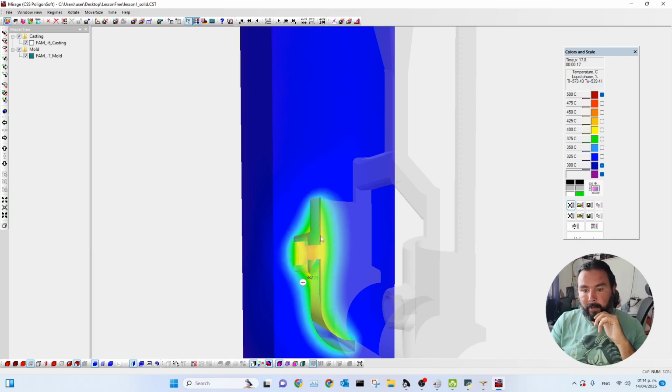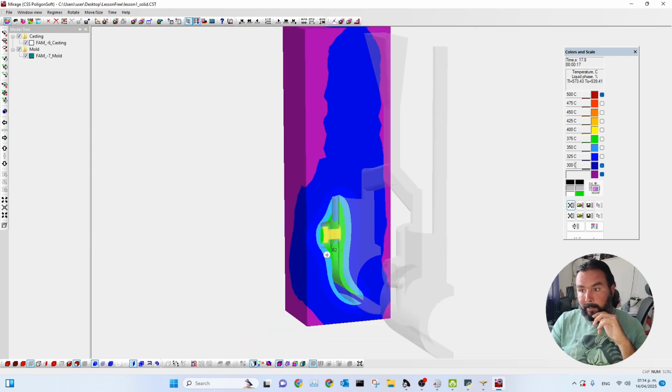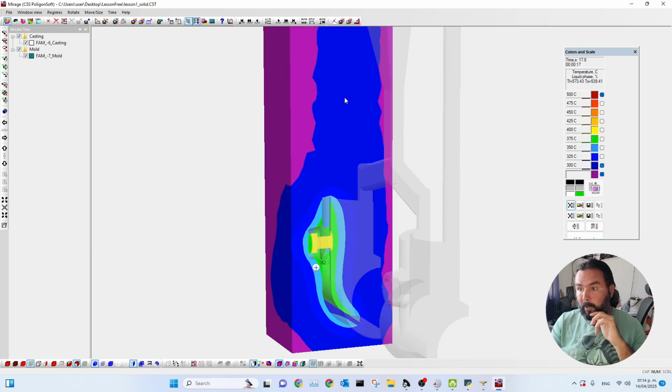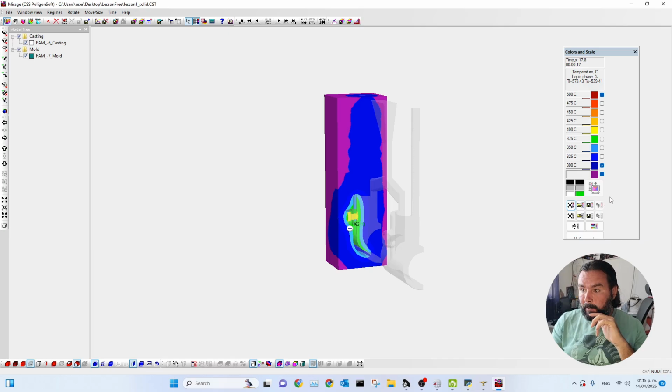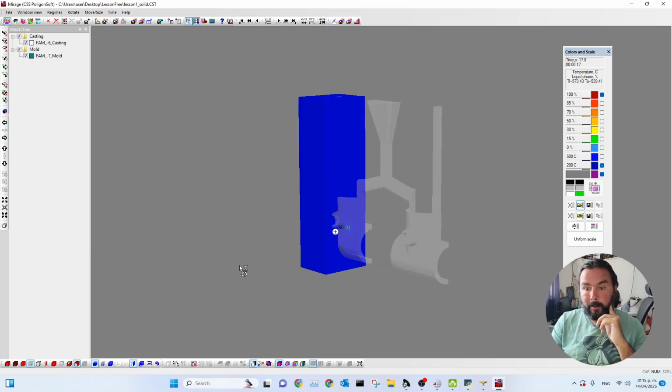In case you find it more comfortable to work with boundaries that are not gradient-based, you can turn off this button here. Then the blocks will have defined limits, without fading, meaning we know exactly that this here is temperatures of 300, this here is temperatures between 300 and 325. This here corresponds to the difference between the two levels. Okay, I'll go back. Let me remove this. With this button, we can return to the default parameters. This allows us to reset the default parameters for the colors, this one for the values. Click Apply, and I return to our default values.